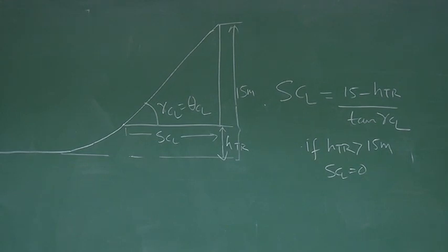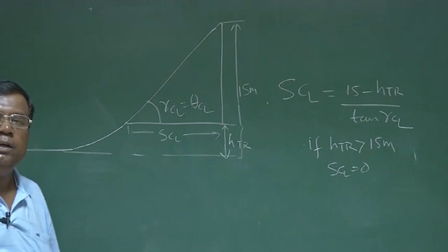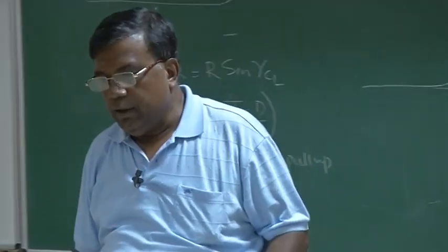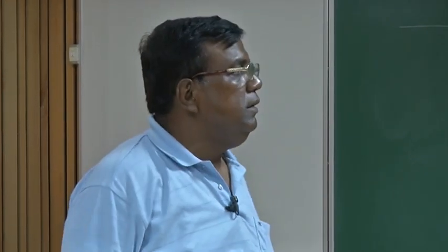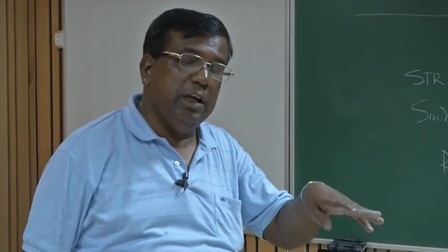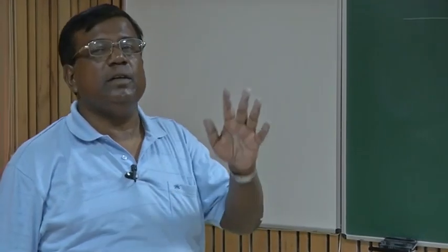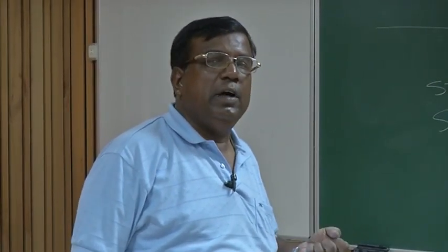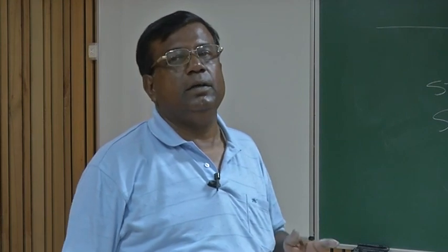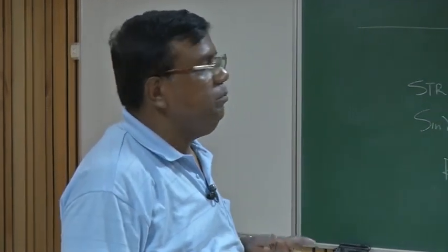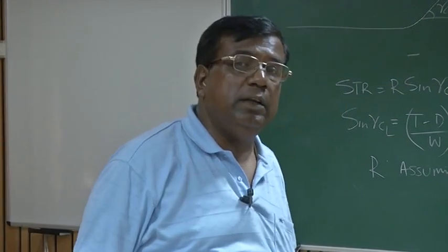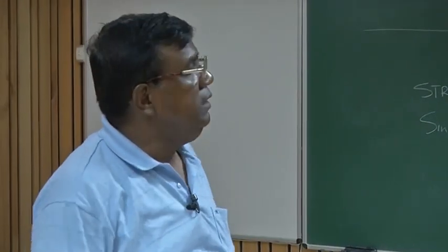Okay? So once you calculate all these segments, you add them up, you will get the takeoff distance. But the question comes, will you only keep that much distance? The answer is obviously no, because midway the airplane can fail. The engine may stop. So you have to keep a margin for that. Generally, you keep 100% margin. If takeoff length is 500 meters, you will keep around 1 kilometer of runway. Clear? Please keep this in mind if land is available. If land is not available, then you may put more stringent conditions. Thank you very much.